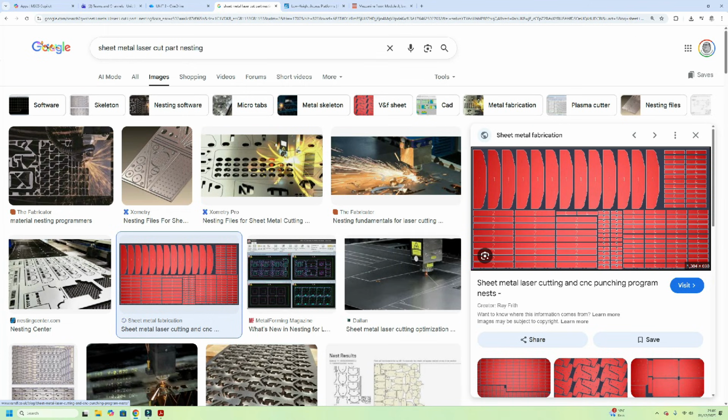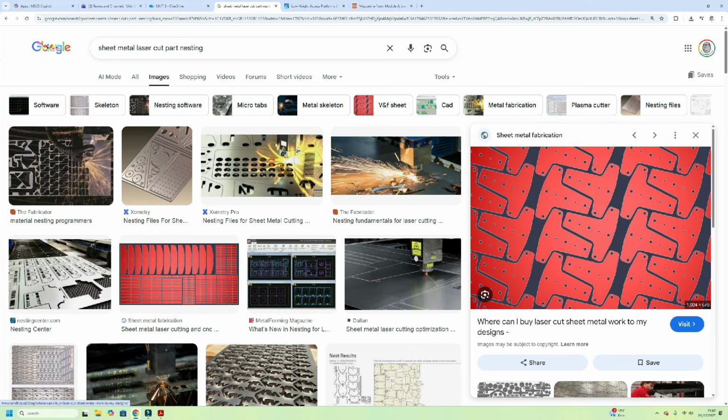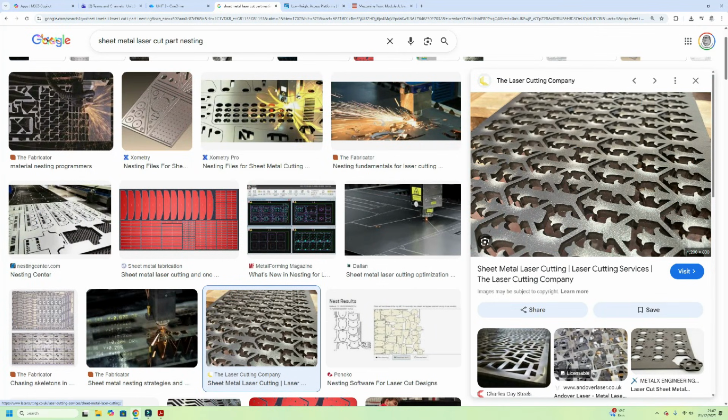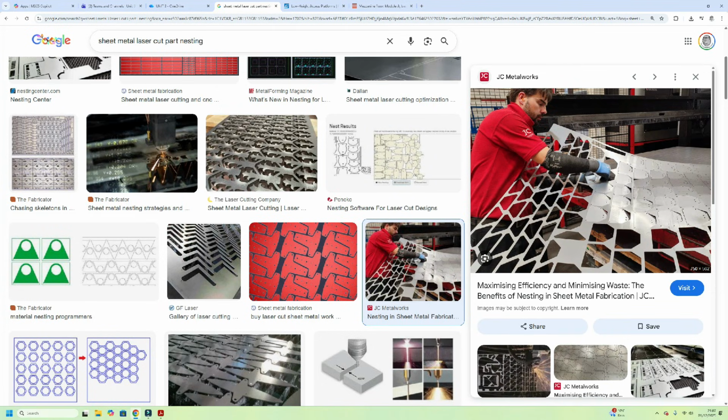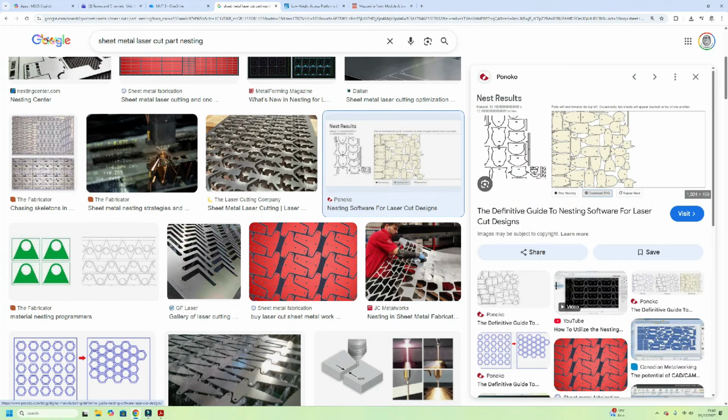There's a typical one. It will lay out as many parts as it can on your sheet, and then cut what you need on it. And you can see, they interlay. That's what the software does for you. And if you look at that one there, beautiful. Isn't that nice? We can go on forever there. So here's another one. And there's the old boy picking them out as well. Perfect. So this would obviously be CNC led. If you're only going to use a part of the sheet, it will save the rest for another job.